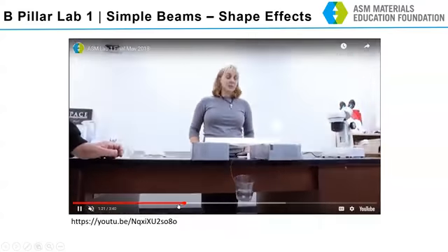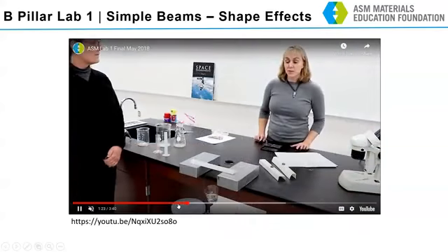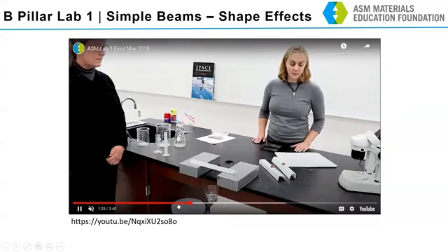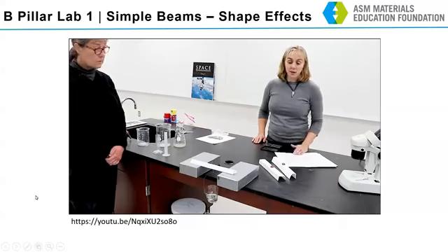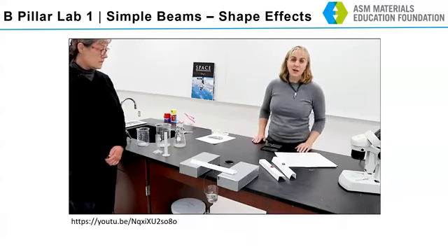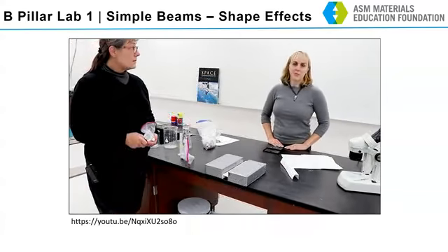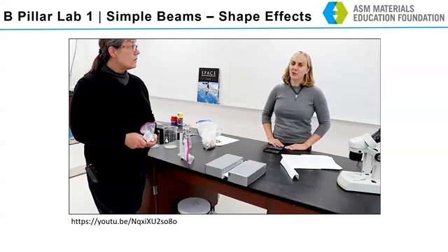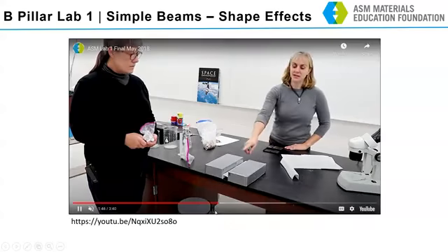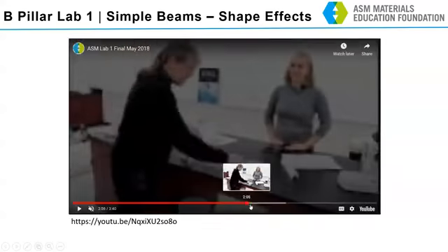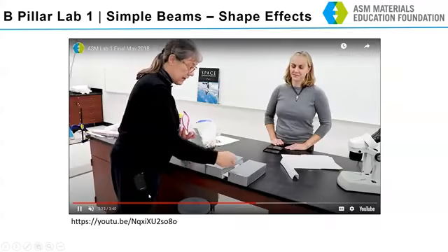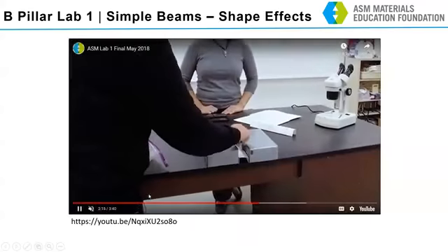What we found was these tend to collapse by the leg folding under, rather than actually crumpling the center of the beam. And we asked ourselves from an engineering point of view, how realistic is this as a simulation of the B-pillar? How often would you be involved in a T-bone crash with both of your doors wide open? There's no support. So we created some ways to support the beams, like both of your doors were closed and latched. And it turns out that it takes a lot more mass to collapse these beams if you keep the legs from folding under.